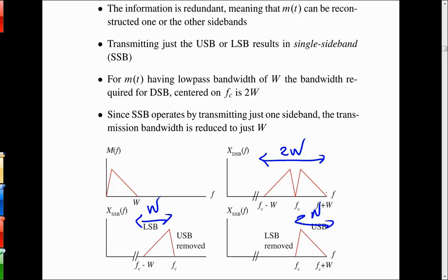And what you can do with single sideband is, this would be like message 1, and you could pack message number 2 right next to it. So you could fill the channel with twice as much information, twice as many messages per hertz of bandwidth with single sideband. That'd be a different signal, though. Yeah, it'd be another user. It wouldn't look anything like it necessarily. I tried to make it look different by squiggling it.